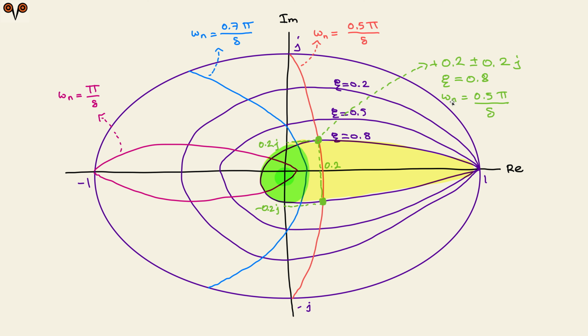Of course, natural frequency changes from application to application, but here I am showing these zeta 0.2, 0.5, 0.8 curves for overshoot, and these are the natural frequency curves. So you need to stay in this yellow highlighted region in order to have zeta greater than 0.8, which is a good zeta value. If you choose eigenvalues with real parts, zeta will be 1, but to achieve a slightly better rise time, you may want to go for 0.8.